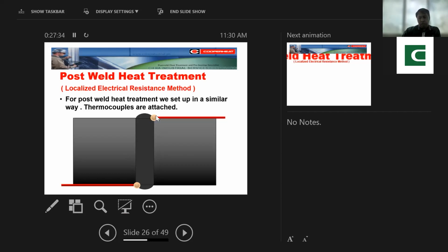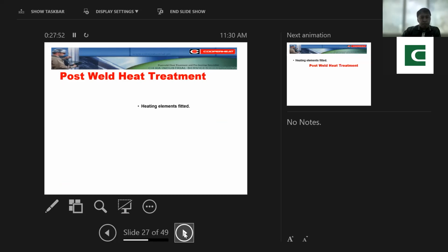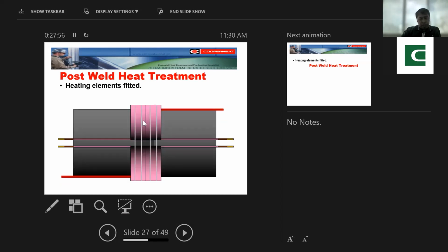The more thermocouple wires, the better for temperature monitoring. So after the attachment of your thermocouple wire using the thermocouple attachment unit, yung TAU, by capacitor discharge, you will place enough ceramic pads.